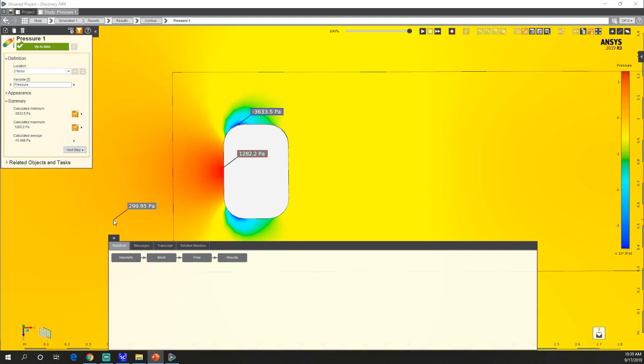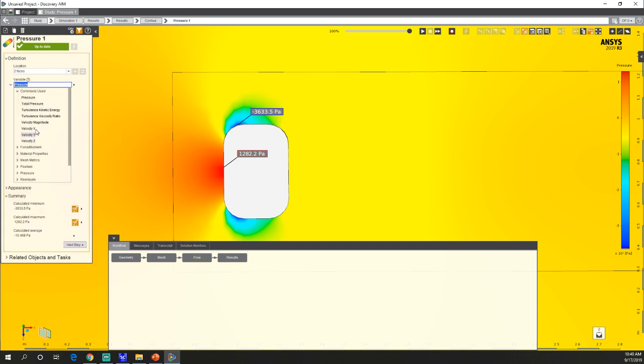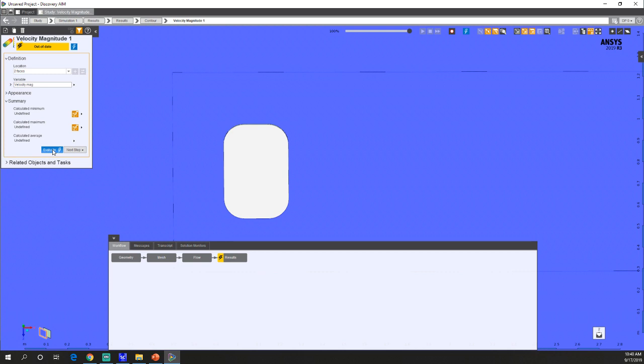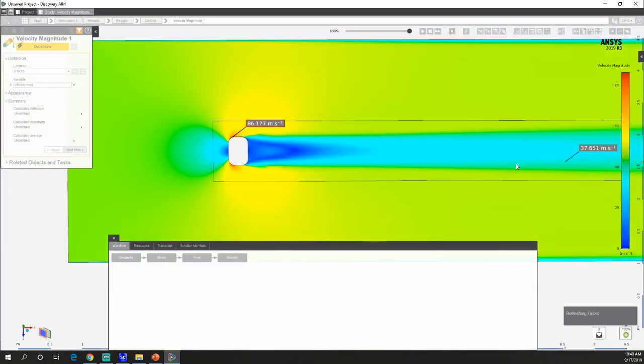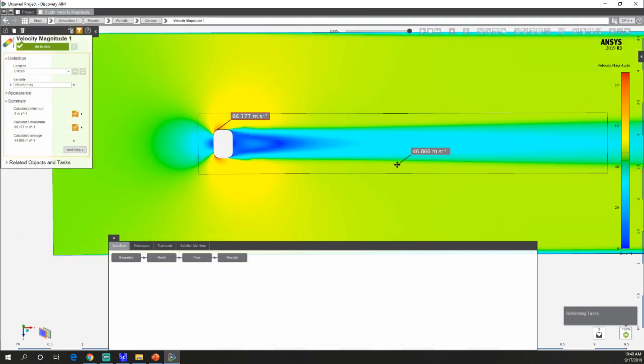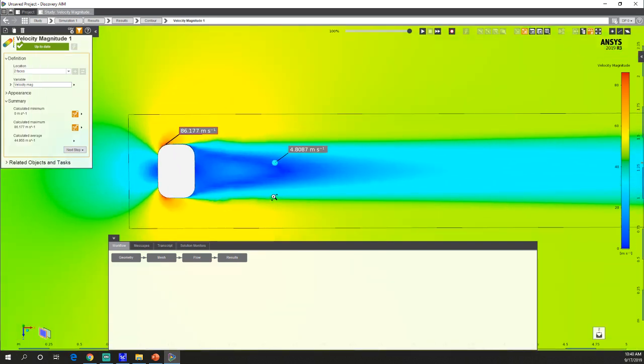These simulations are tricky because the flow isn't always steady. If we look at the velocity distribution, you can see that right now it's predicting this wake that's kind of uniform going back behind our antenna. In reality, it would only ever be like this if the flow is completely balanced on both sides. If there's any sort of instability where flow would slightly be faster on one side or the other, or there's a gust, then you would see this wake start to wiggle back and forth.